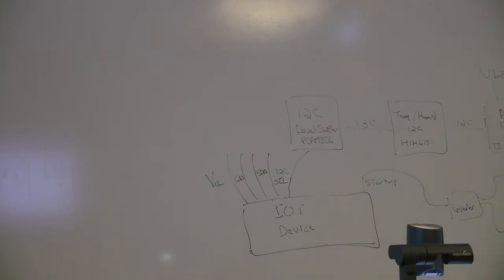I was going to say, I've done a lot of 5-volt and 3-volt I2C on the same bus. You know, you just pull it up to 3 volts. Right. And I've never run into any problems.